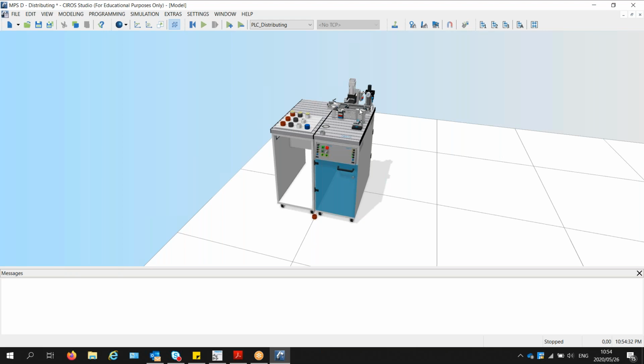Now, if you do that, the problem is that the workpiece will be in front of the sensor, and then it will fall off the conveyor, and then your timer will not work because the sensor has changed state before it could count to 0.